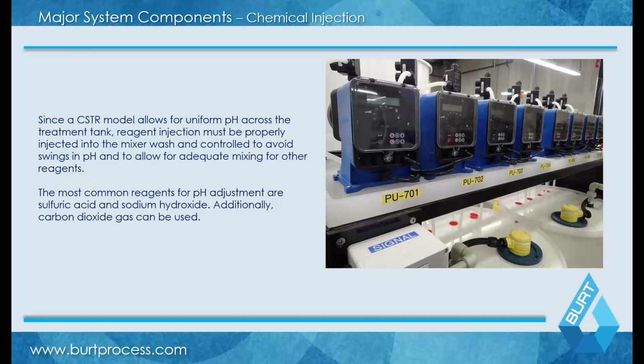By and large, the chemicals that you utilize in your system are significantly stronger than your waste stream. The most common reagent chemicals utilized are 50% sulfuric acid and 25% sodium hydroxide. The reason for the reduced sodium hydroxide concentration has more to do with its chemical nature, particularly if you're in a colder environment. You don't want to have any kind of crystallization in your lines. Sodium hydroxide will turn into a jelly-like substance at around 55 degrees. These chemicals are injected in a much, much lower range than what your waste stream is.